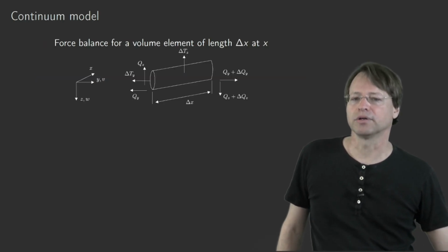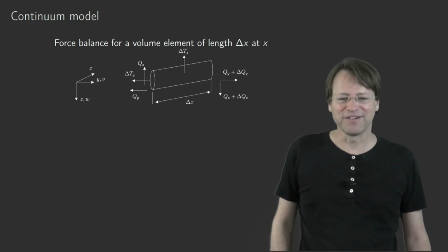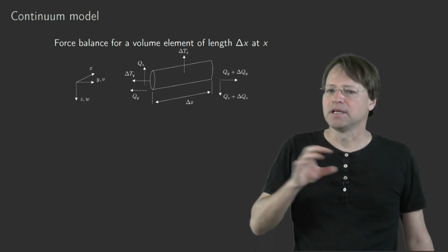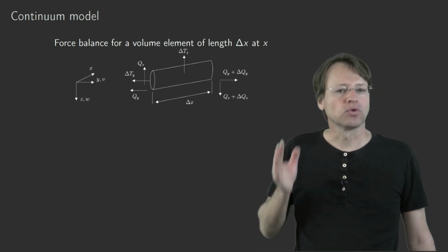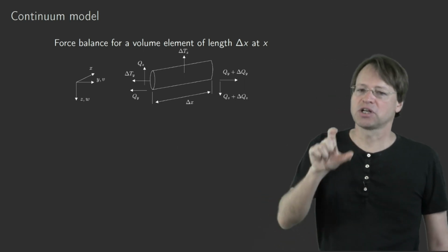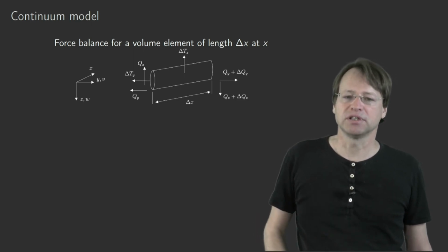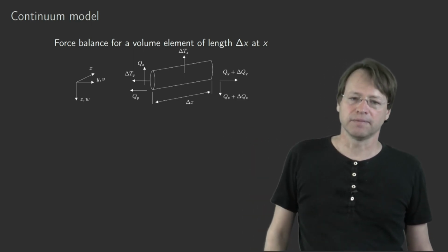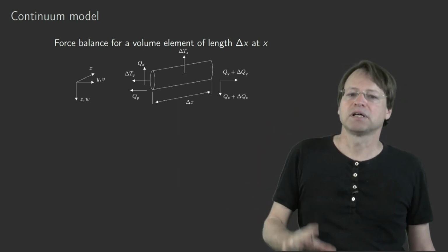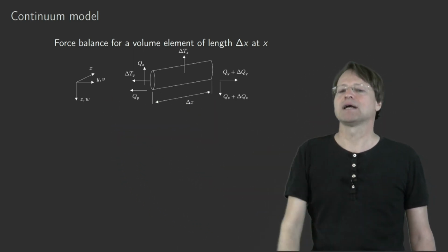So how about the continuum model? For the continuum model, I don't like that approach very much, I have to say, but it's really a simple approach. We cut out one element of that shaft. For the continuum model, there is no disc. There is just a shaft that bends. But that shaft now has to carry the mass properties, described by mass density. There is no single disc anymore to which we apply the inertia properties, but the inertia properties are now smeared over the whole beam, and this is described by a mass density.